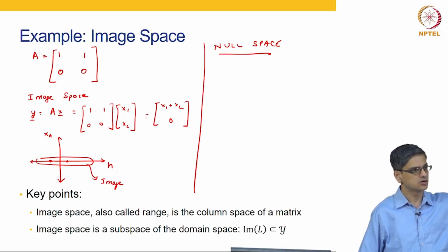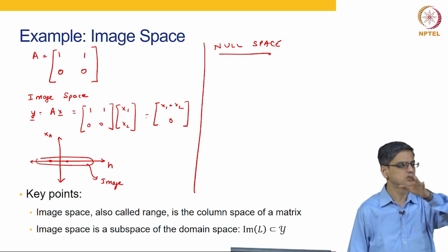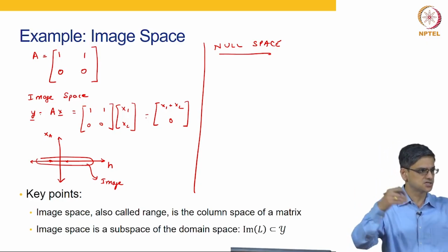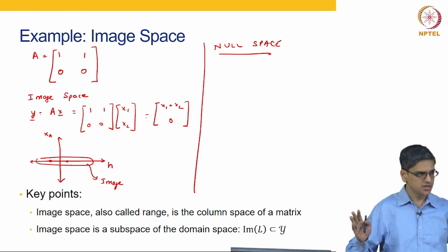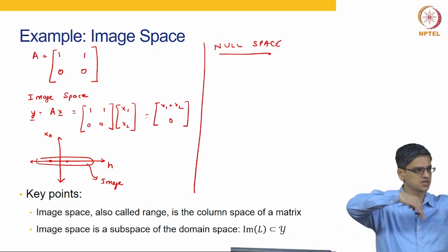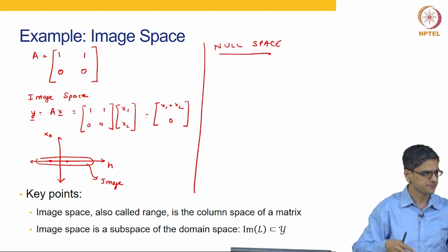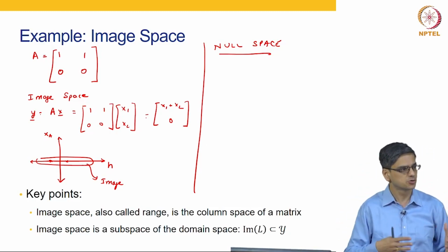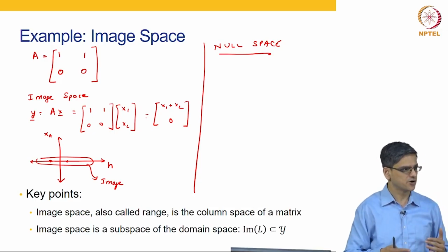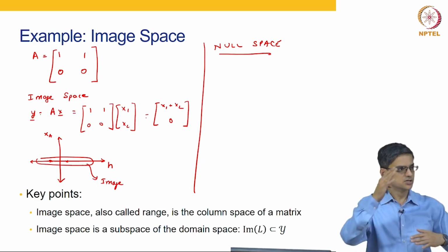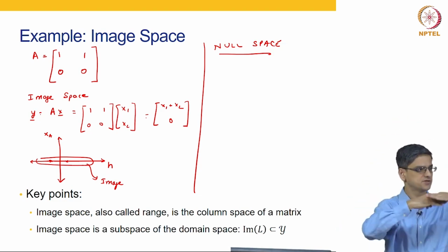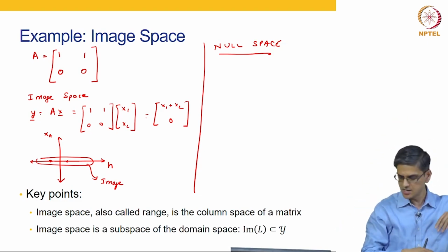So let us say you are mixing a pure A stream and a pure B stream, with concentrations 0 and 1. Initially you have 50 liters per minute and 50 liters per minute coming in and mixing, which means the outlet is going to be 50% A, 50% B. That is your operating point. Along that operating point you have the leeway of going plus 50%, and you have the leeway of going minus 50%.